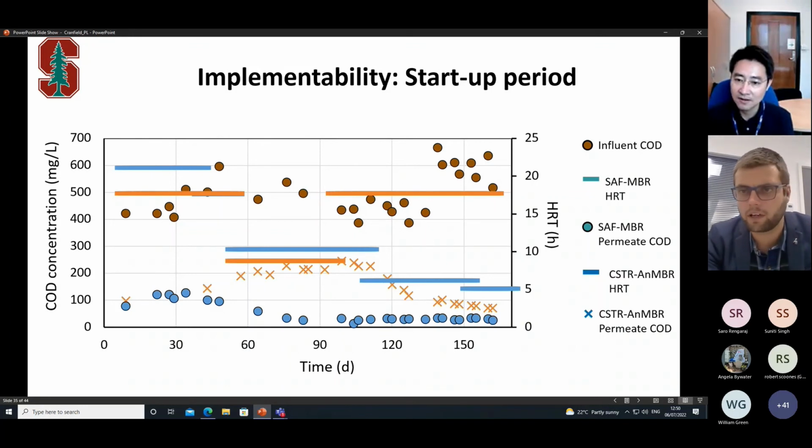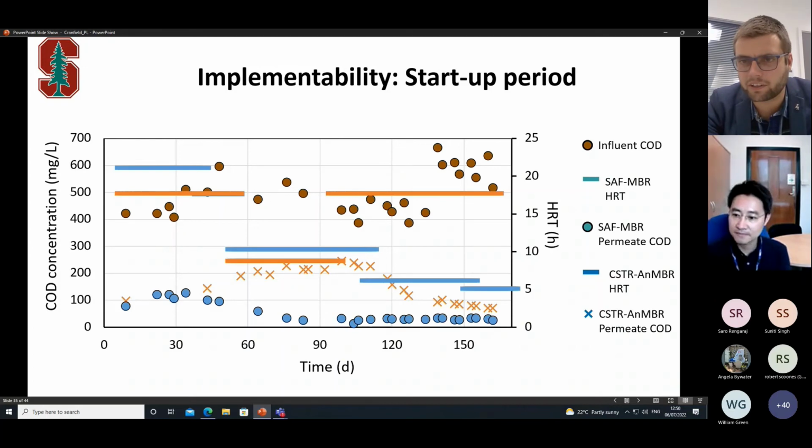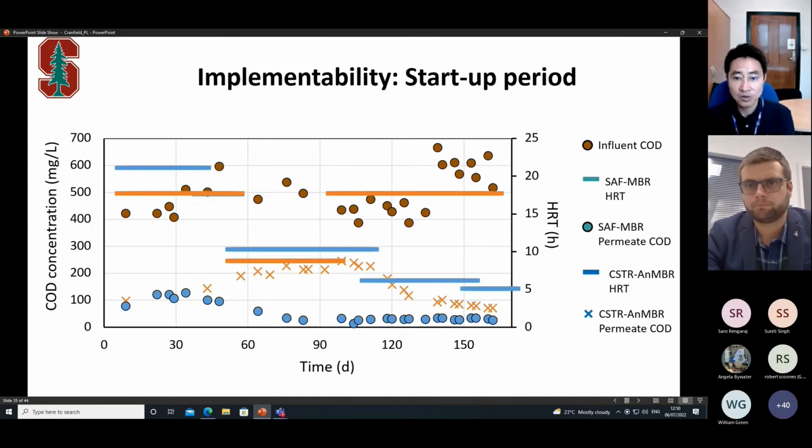Great, thanks, Henry. Do we think that the substrates themselves in the dairy wastewater, long chain fatty acids, etc., could be contributing to that? Yeah, compared to municipal wastewater as well. I think so. If you have more soluble substrates, I think it worked quite well. But you probably have to begin a little bit slower, with a longer SRT, build up the biofilms, and slowly move to your target HRT. Building up the biofilms is really key information so that you can reach your goal.